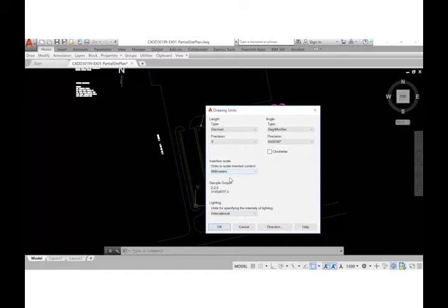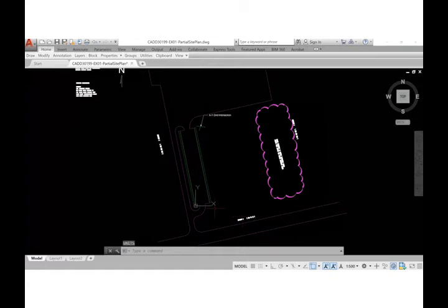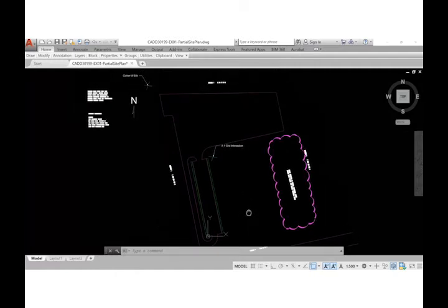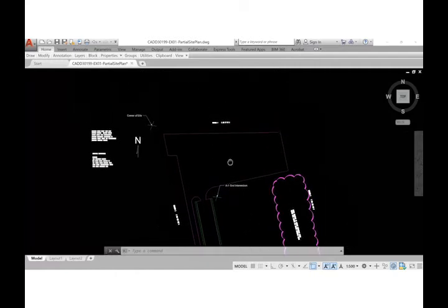Okay, that's good. Sometimes even if we have millimeters here, some surveyor, right? Some surveyor, when they use dimension, they use 1 equals to 1 meter. Okay, so we need to check that as well. So what are they using here? Okay, so let's see. Well, we do have here 161.953 meter, right? So the unit being used is meter.